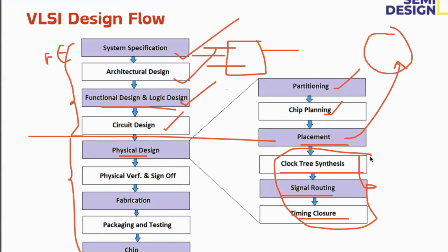Every digital circuit has its own clock, right? If you go to SOC level, those are very complex things. So there we need to check all the different clock signals, and signal routing: whether all signals are matching with the inputs and outputs of different IPs or not, and timing closure. We need to check all these things with the different teams that are available.